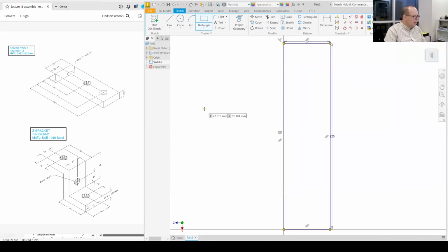Zoom to go out. So now we can just extrude it and put holes in it, but we can also just put the holes in right away. If we start down here, it's going to be easy to figure out exactly where that hole has to be. It says 15 from both sides, so we can say we want to have 15 and, okay, minus 15. That's fine too. And then the size, it says diameter of 10.